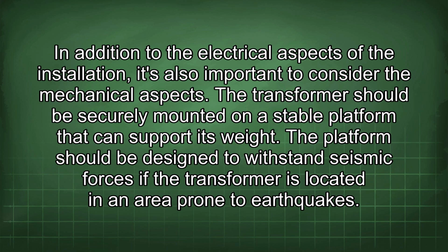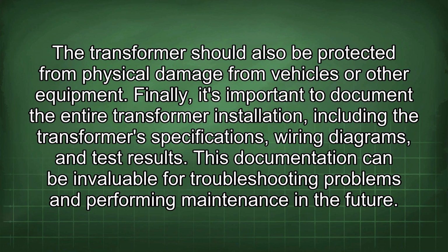In addition to the electrical aspects of the installation, it's also important to consider the mechanical aspects. The transformer should be securely mounted on a stable platform that can support its weight. The platform should be designed to withstand seismic forces if the transformer is located in an area prone to earthquakes. The transformer should also be protected from physical damage from vehicles or other equipment.